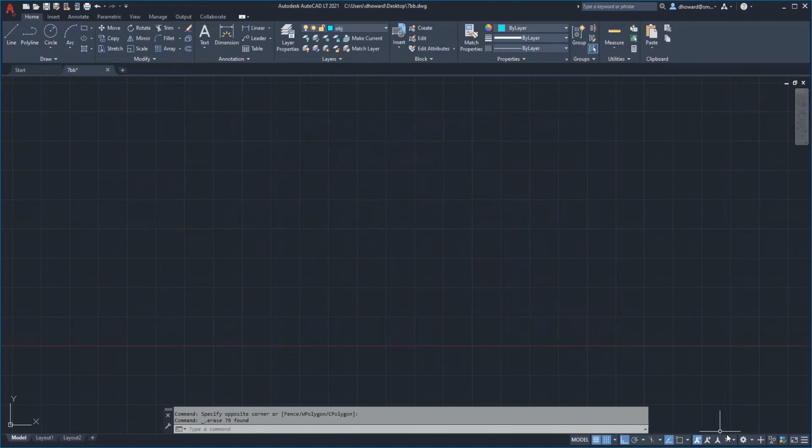Okay, what snaps have I got on here? My grid, and yeah, that'll work, grid snap. And I'll be going back and forth between that and my object snap, which is the F3 button. And the grid snap is the F9 button, so I can go back and forth between those two, just hitting those function buttons.